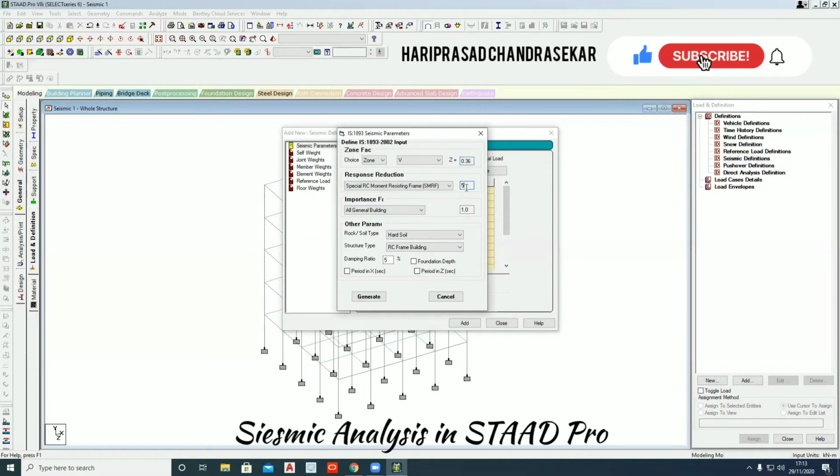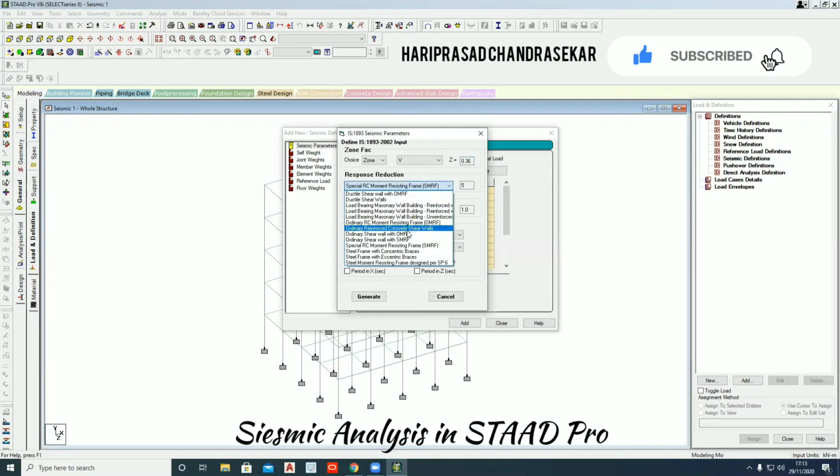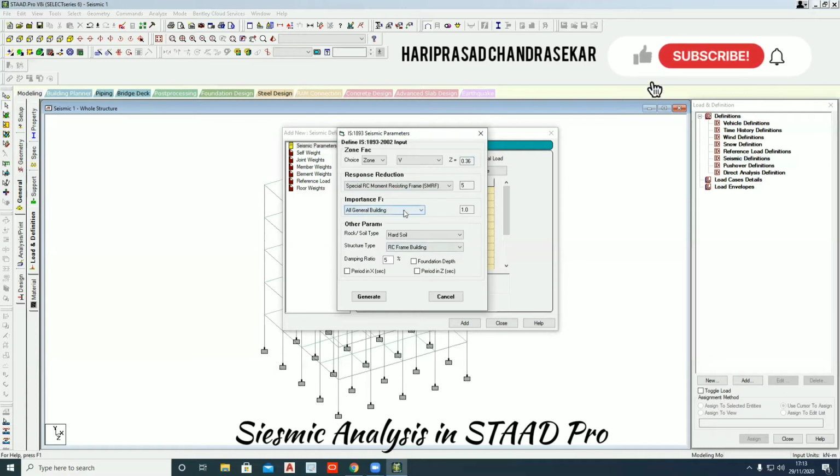Sometimes we can't change, even this 5 also we can't change. It depends on the option that you choose. Option 5 only, and it is a general building. If you want to consider this as an important building, you can select important building, in the sense if it is a hospital or an institution where everyone works every day. So the factor of safety will be 1.5. For a general building, it is 1. For an important building, the factor of safety is 1.5.